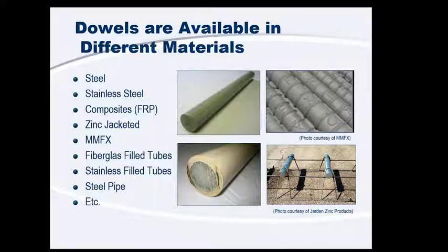One of the reasons that this has been brought on is when we have long life pavements, we need to start thinking about what kind of materials our dowels are made out of to make sure that they don't erode. We want to make sure that our dowels can outlive the life of our pavement, especially when we get into 50-year design life. If we have an erodible dowel in there, that can lock up our joint and ruin the performance of the joint. So we need to make sure that we match the dowel to the application as well. There are a lot of different types of these that have been developed, and these long life dowels have performed very well, and some of them don't have significant increases in cost as well. So if you're designing a long life pavement, it may be something that you want to consider.